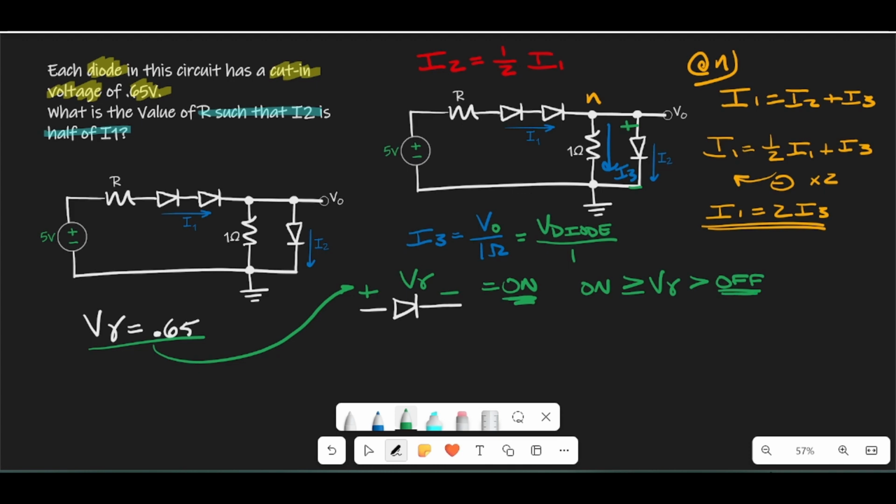I repeat. Once on, a diode maintains the turn-on voltage, no matter how big the source is. If the diode receives anything less than the turn-on voltage, then it's, well, off. So when a diode is on, it lets current pass freely through it, basically acting like a short circuit. Except instead of it being 0 volts, it's a short with the turn-on voltage holding it still. You can redraw an active diode as a short if you want, so long as you label the turn-on voltage across it.